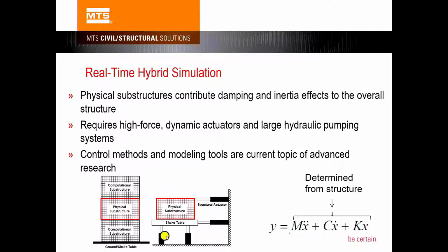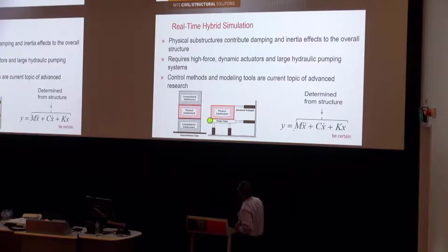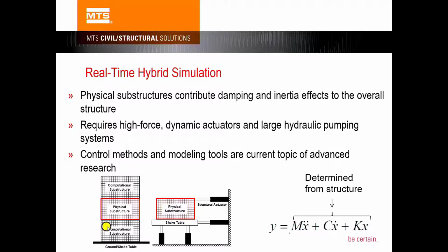So this has to be real-time hybrid simulation because this is an inertial-reacted test, and you have to model the acceleration and apply the acceleration in real time, to be able to load the midsection accurately. So this is a real-time hybrid simulation example.